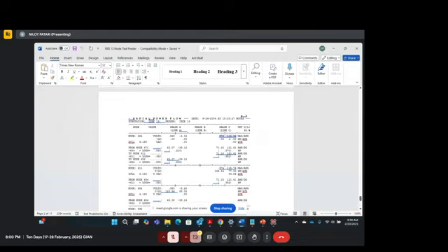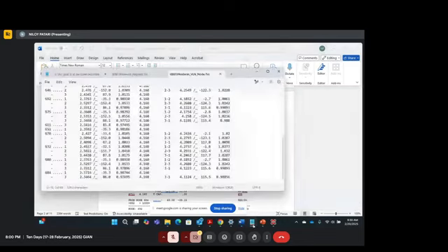So at 684, you have this 0.988 at phase A, and at phase C you have 0.976, right? So at 684, it's like 0.9874 and 0.976, which is pretty close to each other. So you can pretty much say the voltages match with each other.